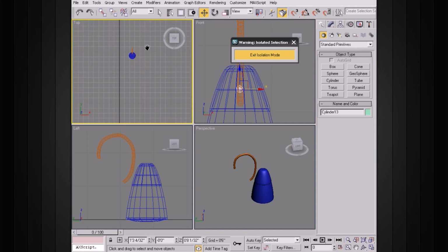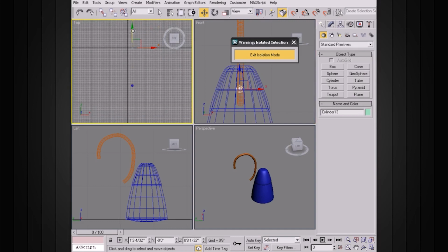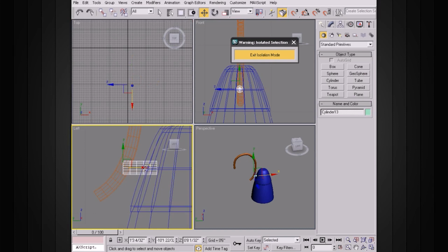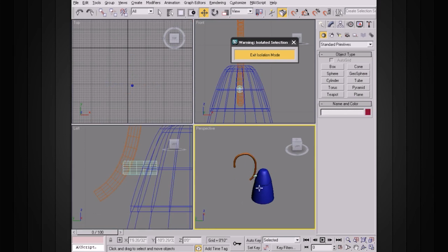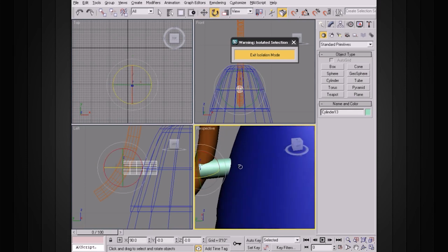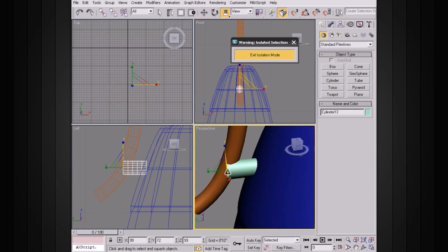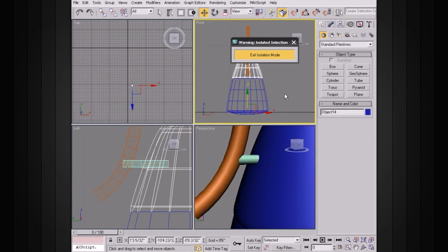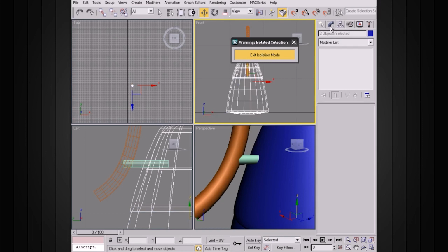And let's find it in here. It's actually over there on the origin there. So I'll go ahead and move this until it is kind of attaching the shape that we just created and our lamp. You can see it's a little bit too wide. So I'll go ahead and scale this down until it is kind of encompassed by that entire thing. Okay, let's go ahead and now attach these guys. So I'm going to go ahead and turn off the smoothing.